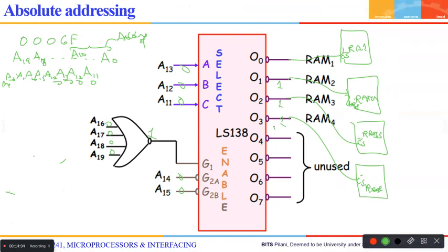If the memory chip is capable of giving 16-bit data at a time, then there is no problem, and you can interface the way you have learned now. But where your memory is byte addressable and your microprocessor is 16-bit, you have to go for a different method called even and odd addressing.